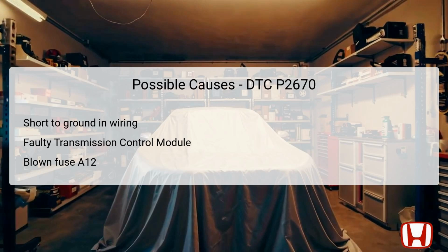Lastly, a faulty TCM potentially contributes to this DTC. If the module isn't functioning as intended, it may not process the voltage correctly. Understanding these causes is the foundation for effective troubleshooting and repair.